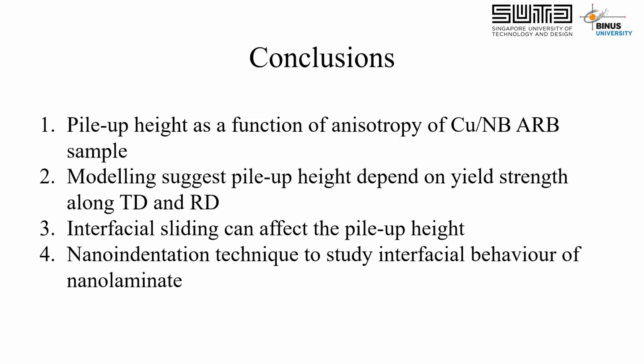So in conclusion, pile-up height indeed depends on the anisotropy of the copper niobium ARB sample in RD versus TD. Both modeling and experimental results show that pile-up height is actually substantially higher in RD compared to TD. We propose a deformation mechanism that might involve the interfacial sliding difference between the two, and thus the indentation technique can be used to study interfacial behavior of nanolaminates.